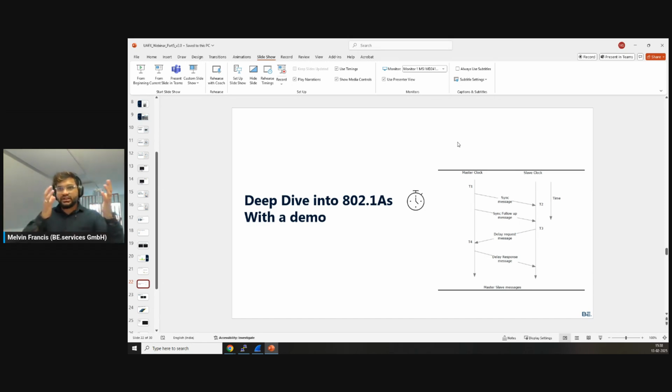There are also transactions while they decide who's the best master clock using the BMCA algorithm. During those times, there are announce messages. Everybody announces their capabilities, and according to the capabilities, you put it through the funnel of the BMCA algorithm, and then you finally get out who is decided as the master.